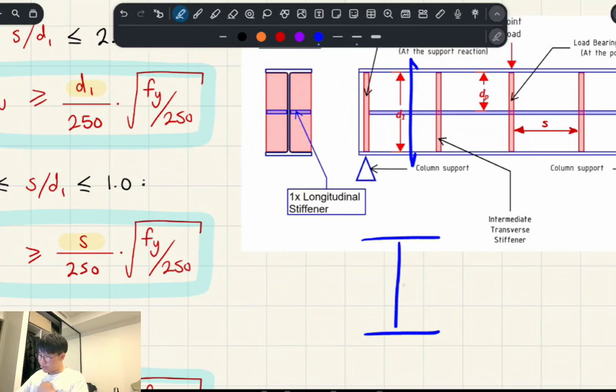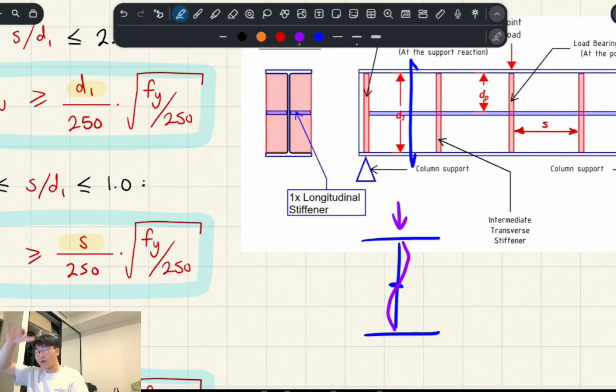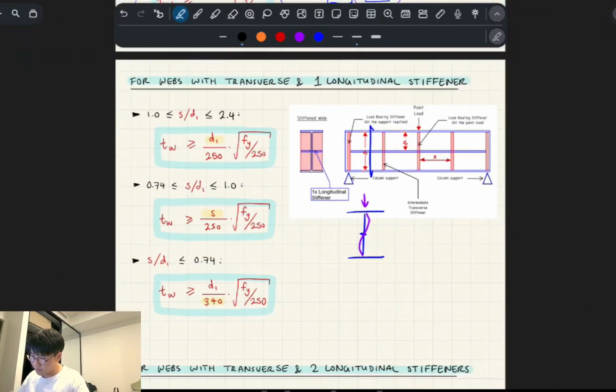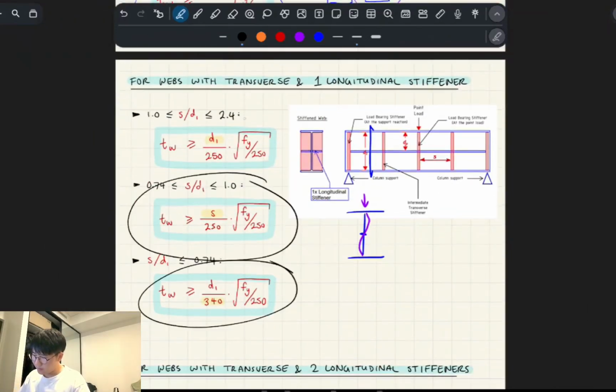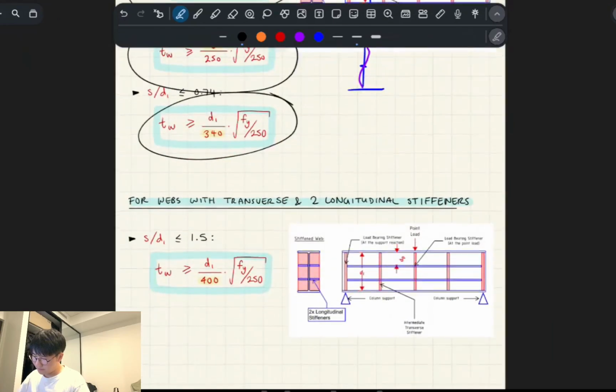You've just braced your column right here. So now, instead of buckling in compression like a full C, this now has to buckle in an S shape, right? Anyway, so different properties and therefore different formulas.